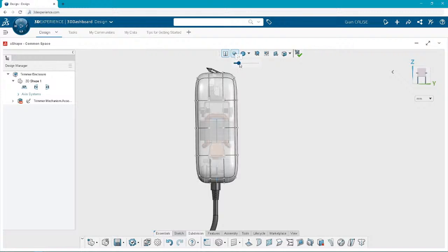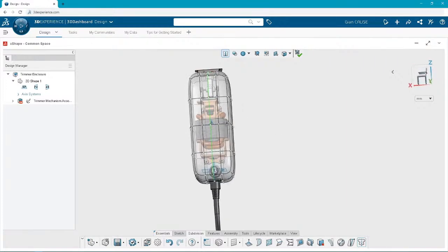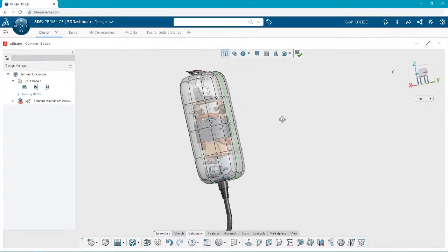Now I'm going to turn on transparency a little bit. I want to be able to see these components inside so I can model around them. And then I also want to just add symmetry about that YZ plane we were talking about. That's going to put a new loop around our model here, and it's going to show in green so that I know there's symmetry turned on around that loop. So everything will be acting about that one plane, our symmetry there.